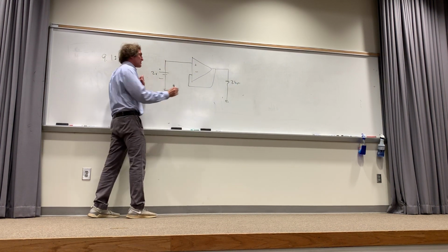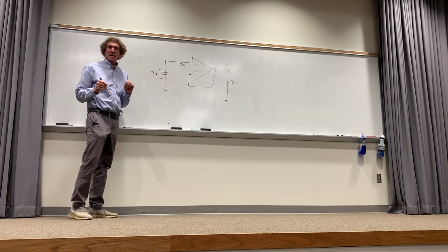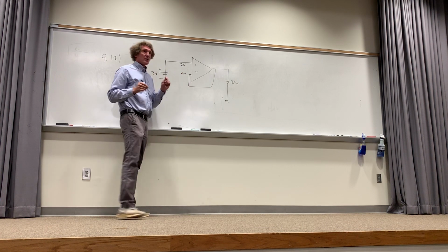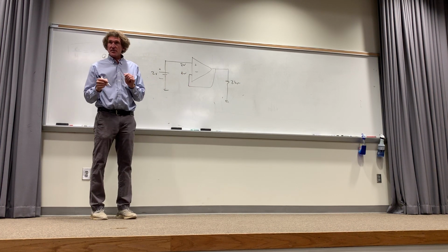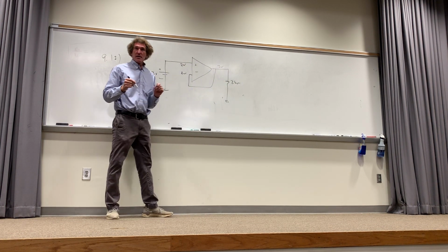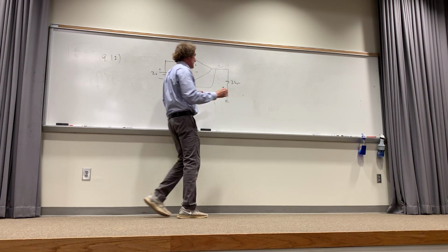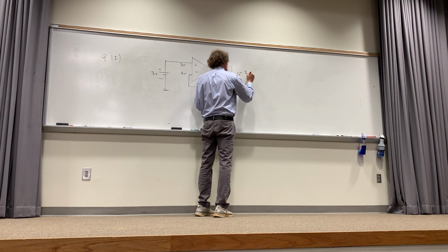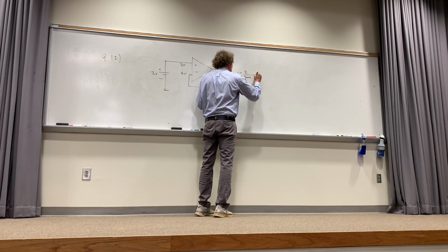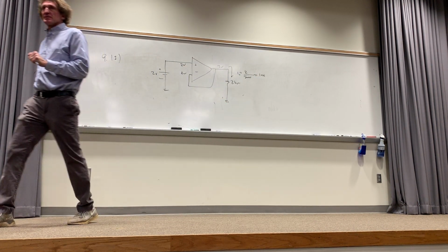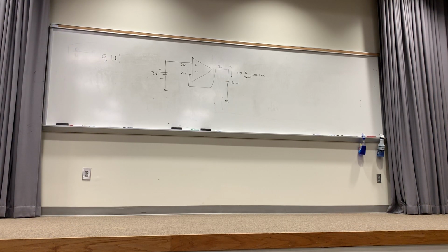Now, you, by this time, know the game. If there's 2 volts here, there's 2 volts here, right? And if there's 2 volts there, there's 2 volts here. Agreed? And if there's 2 volts here, there's 2 volts here. Agreed? And that means the current here is just its load is simply 2 divided by 2,000 or 1 milliamp. So now the logical thing you're thinking is why do you even bother putting an op amp there, right? Here's the reason, listen.